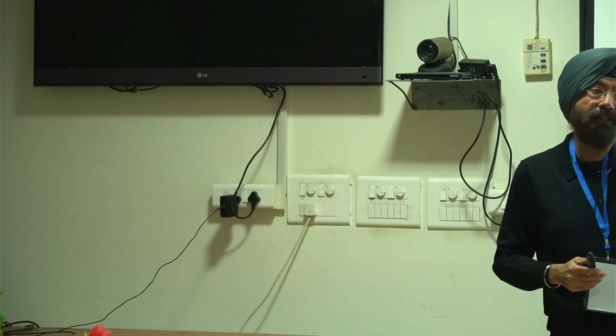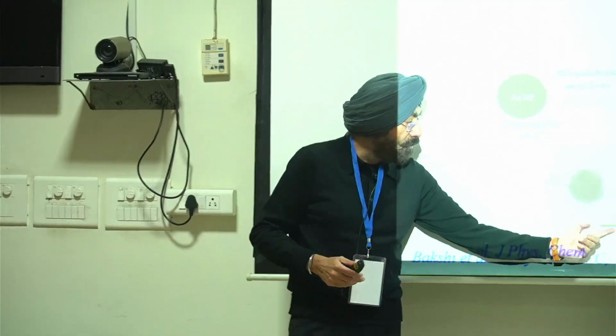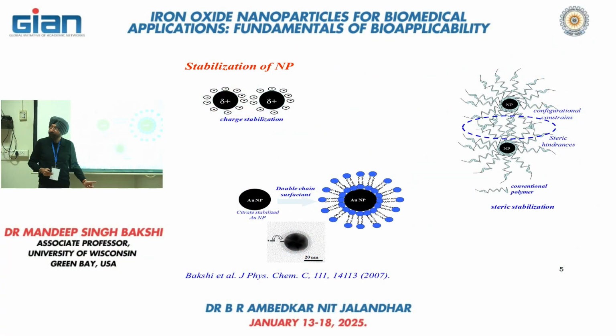But in material science, when you are going to take the image through the transmission electron microscope, the best way to read the image is, first, you must focus your attention on the scale bar. So this much length refers to 20 nanometer. It means by concentrating on this much length, you can check the diameter of the particle. So you see that the diameter of the particle may be 25 to 30 nanometer, right?